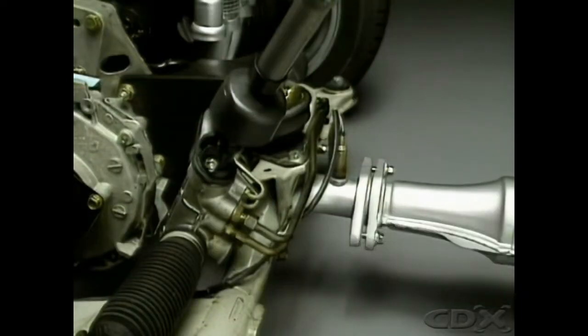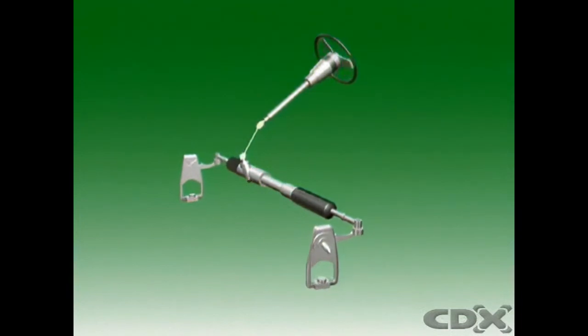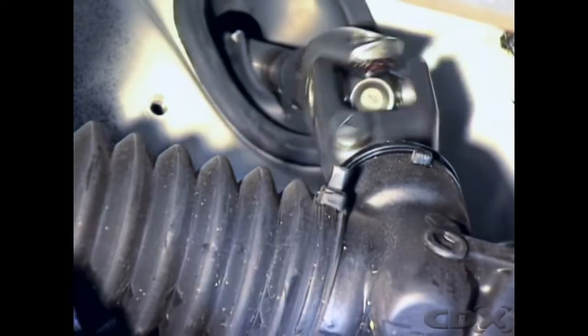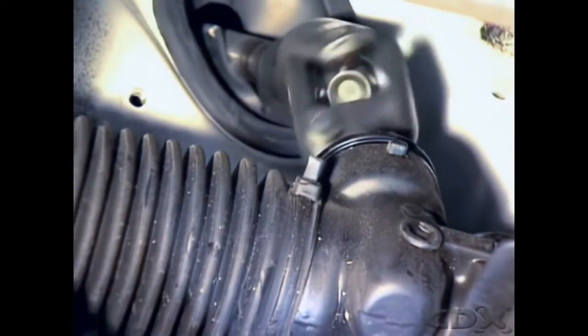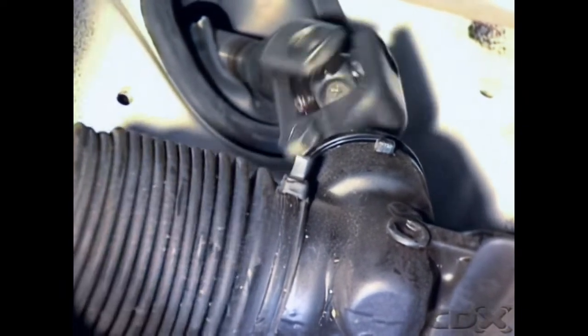Rack and pinion type steering gears are used because their construction makes them compact and lightweight. Their steering response is very sharp because the rack operates directly on the steering knuckle, and there is very little sliding and rotation resistance, which gives lighter operation.